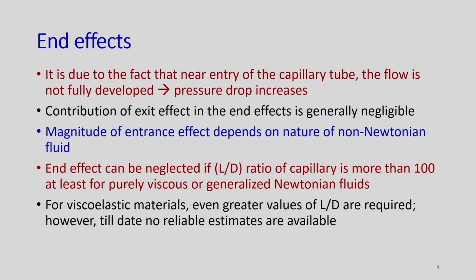So, the first one is the end effect. The end effect is usually because of the entry effect and exit effects. We know that near the entry of the capillary tube the flow cannot be fully developed, and obviously the pressure drop will increase compared to the pressure drop under fully developed conditions.